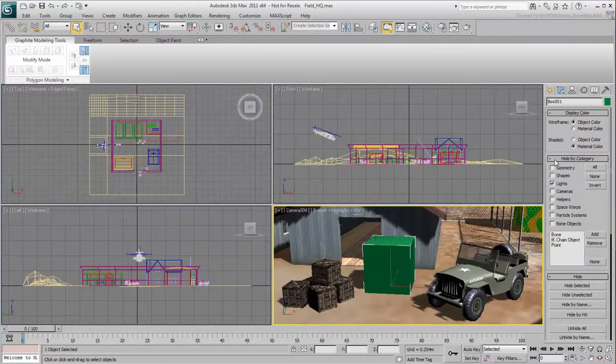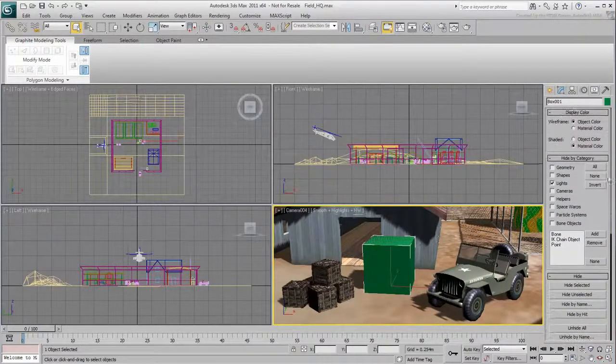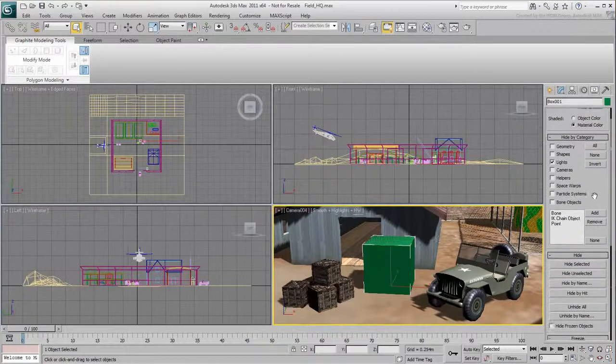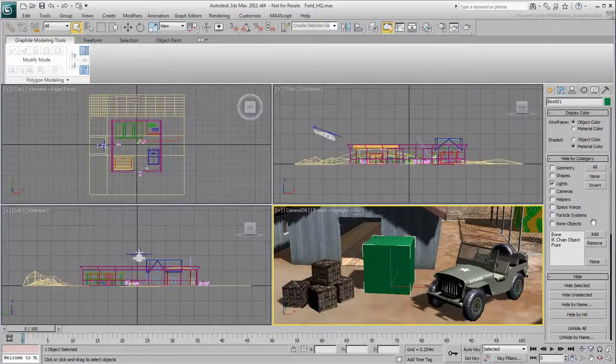When the information is too lengthy, you can scroll the panel up or down, either by dragging the scroll bar or by placing the cursor in a blank gray area and dragging up or down. You can also click the panel and use the mouse wheel to scroll. To access many rollouts at the same time, you can drag the command panel to the left to give it more room.